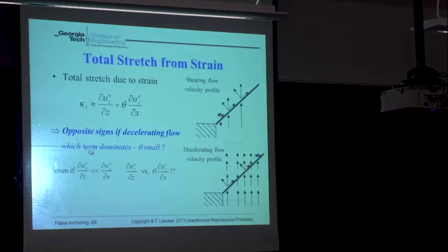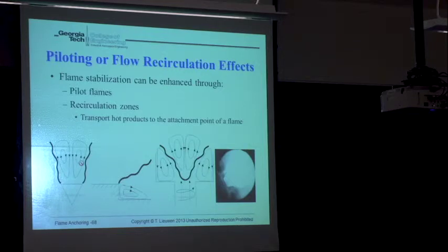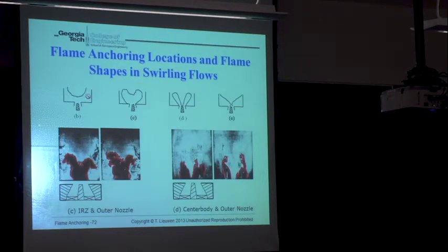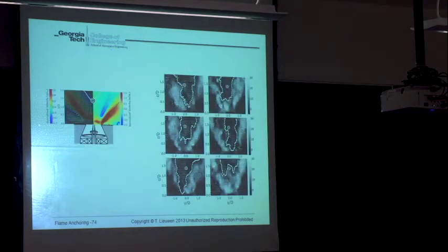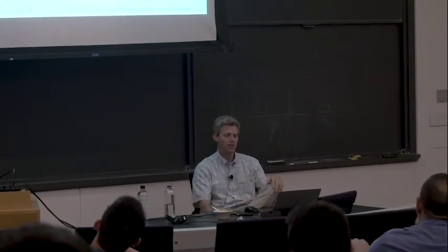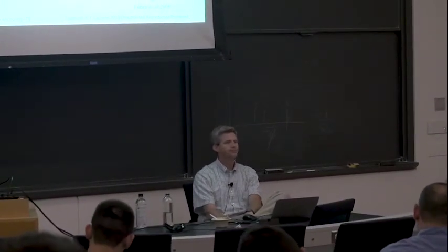this flame, I mean, boundary conditions always matter. I don't mean to knock boundary conditions, but if you put this thing in a tube, I don't think the blowout limits would be that sensitive to your downstream boundary condition. The swirling, it could, not necessarily, but it could really change what blowout looks like, or what your flame shapes look like close to blowoff. So I just leave that as a final word of caution. I bear scars on my body from making mistakes like this. Does anyone have a question?